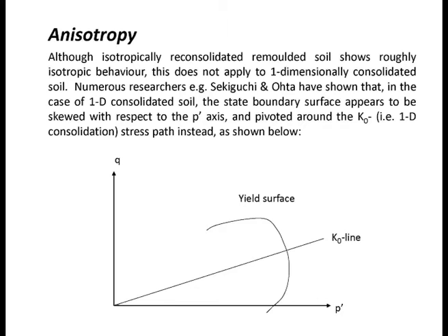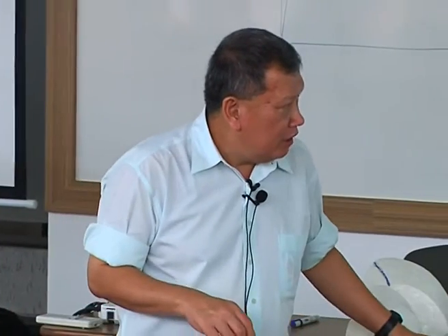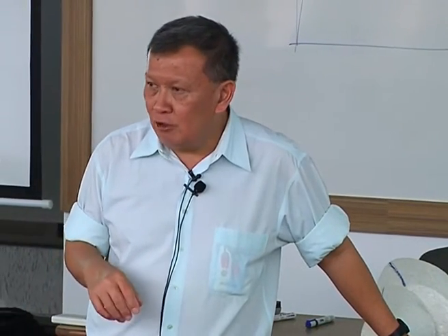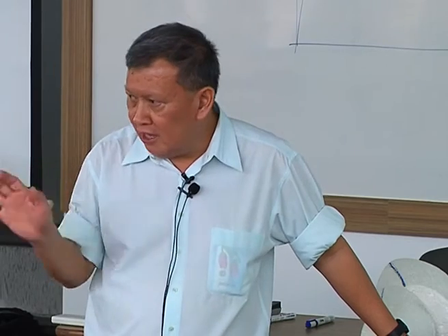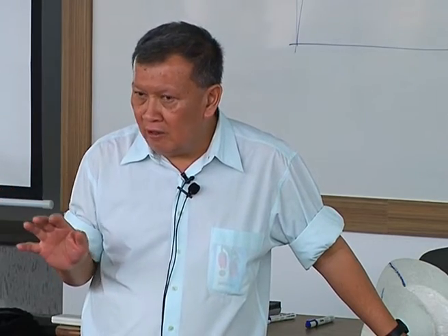The only thing is that anisotropy is a very, very wide field of study. You've got inherent intrinsic anisotropy, you've got stress-induced anisotropy, you've got all kinds of anisotropy. So it's not a topic you can easily put your finger on and say, maybe I'll give you some guidelines. So for this reason, my only advice is that if your soil is highly anisotropic, you may find that none of the models you used in Plaxis, GeoFEA can deal with this anisotropy. Not easy to deal with.